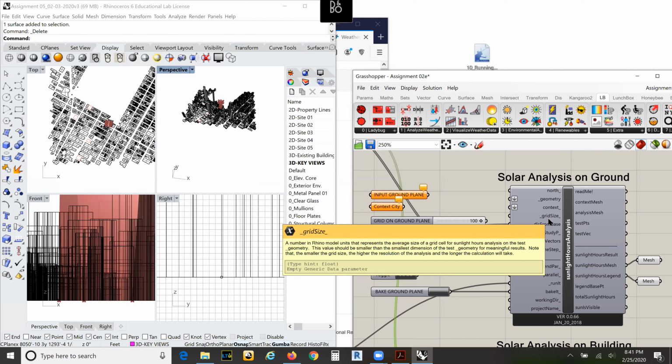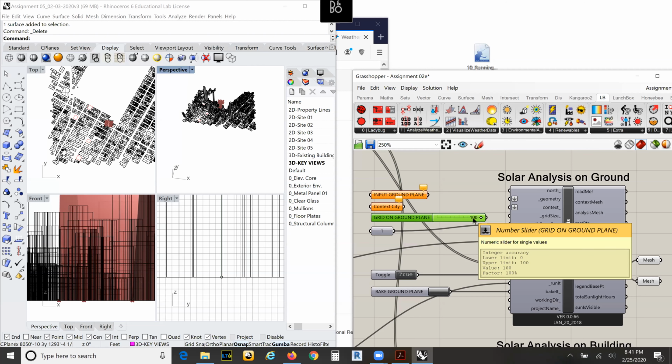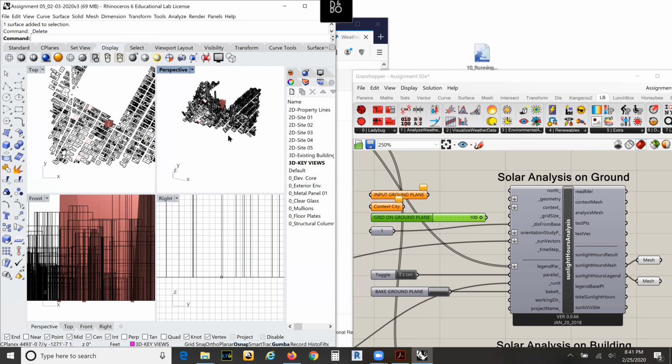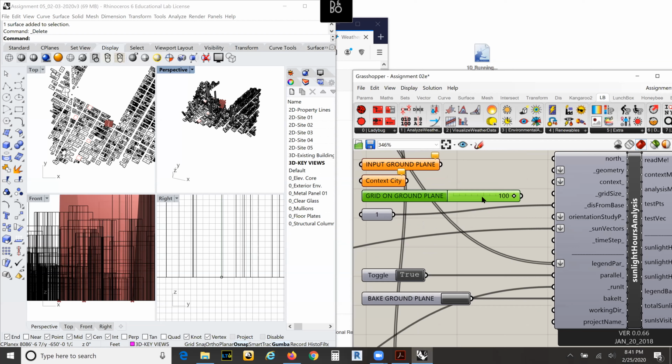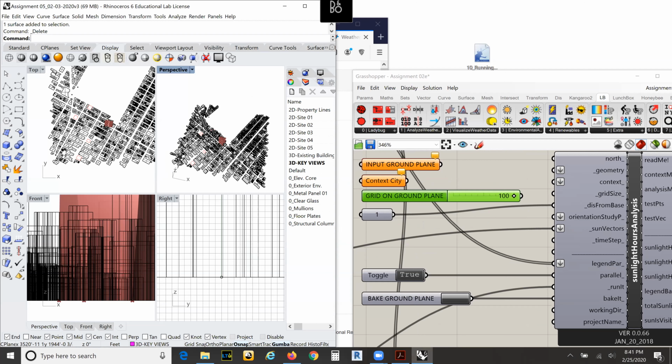And so we set the ground plane at, in this case, a 100-foot by 100-foot grid. That's a huge grid. And I'm assuming we're all going to stay in feet for this. Please stay in feet. Don't switch this to inches, because this will blow up the machine, because it'll read it as 100 inches by 100 inches. And that's an entire city, or a quarter or eighth of a city. So it will chug for a long time.